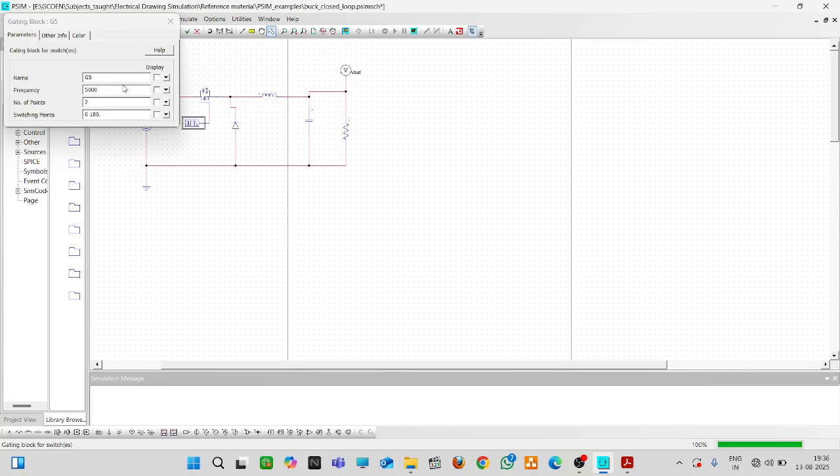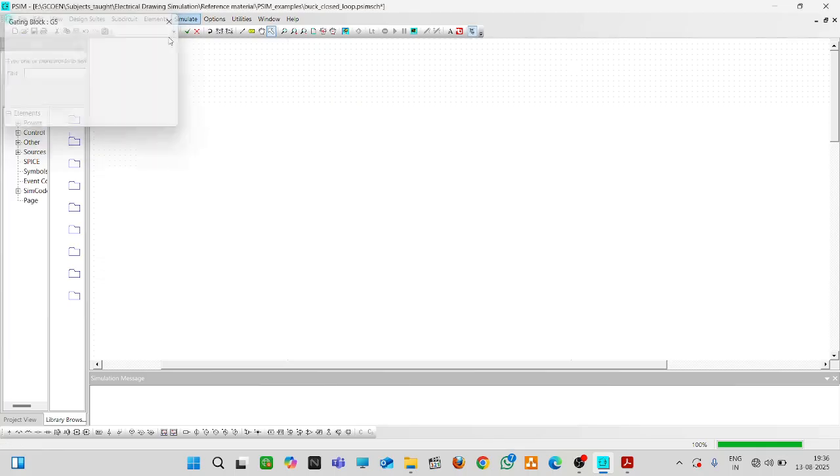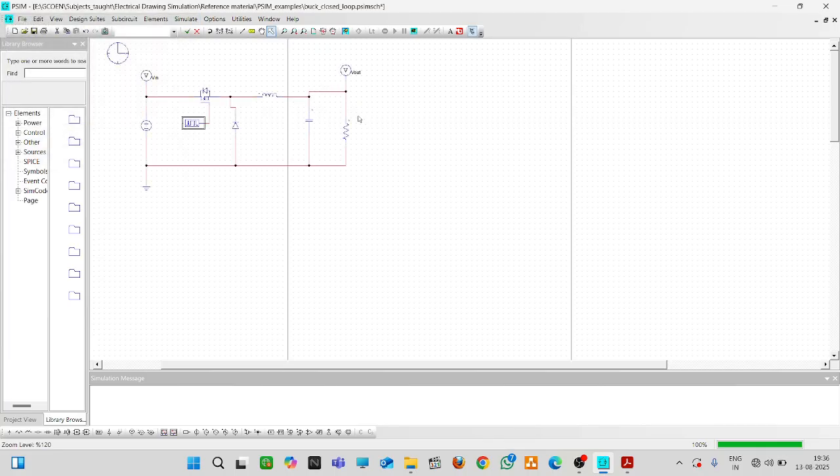But before that, the pulse generator, right? Here you keep it as 25 kilohertz. You can see that the complete cycle will be from 0 to 360 degree. If you are keeping it as 0 to 180, it means that there is a duty cycle of 0.5. So 0.5 into 24, you should be able to get 12 volt.